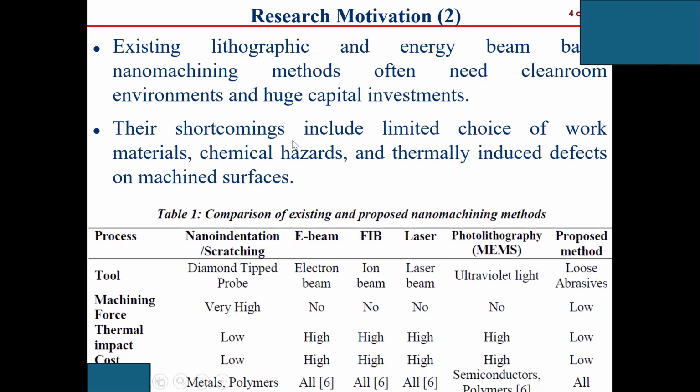Their shortcomings include limited choice of work material and also chemical hazards associated with lithographic and energy beam based nano machining, and also thermally induced defects. This is especially for the energy beam based nano machining, which leaves thermally induced defects on the machined surface.